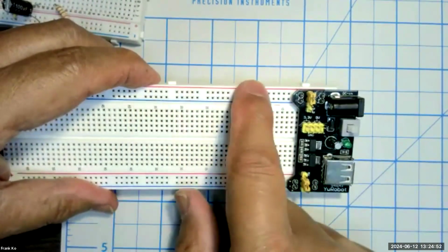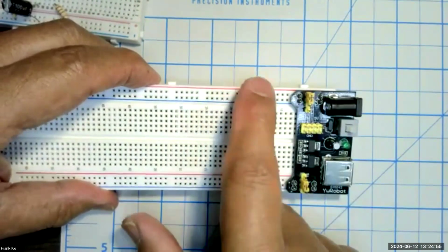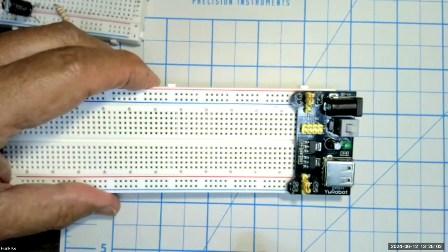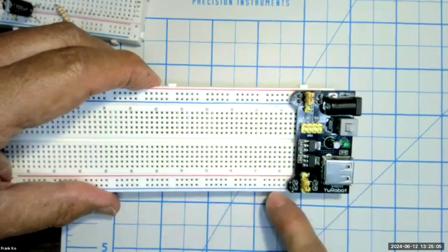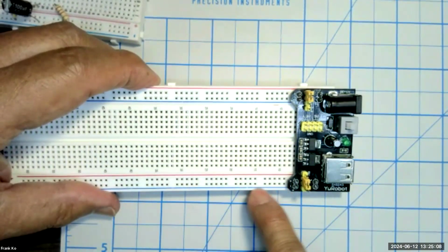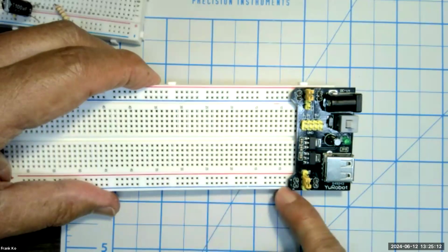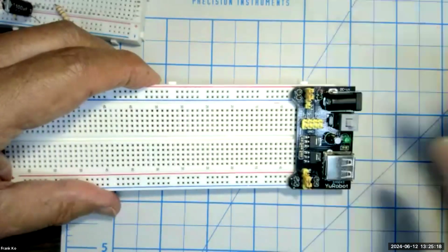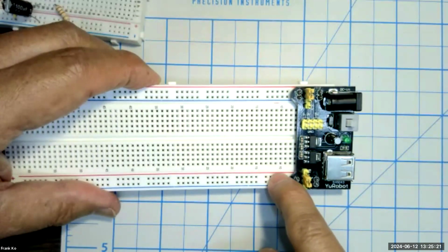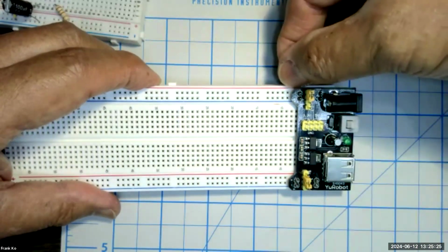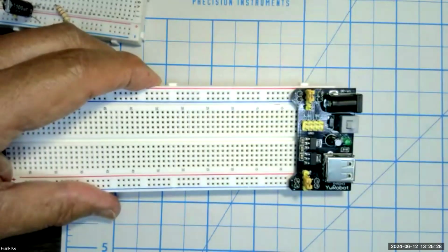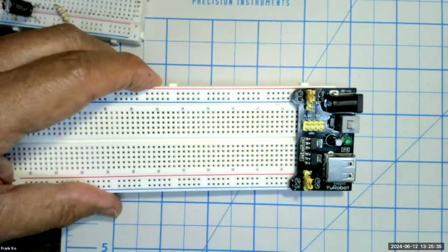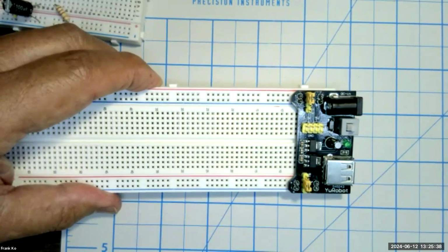This will be the power rail that will be supplied by the 5-volt source. And we will be connecting to these 2 rails. For convenience purposes, as the circuits continue to be more sophisticated, we can also use this blue rail here as a connection to completing our circuit. This blue rail and this blue rail are continuous with each other through the board, but there is no voltage that is supplied to this red rail. The voltage is only supplied through this upper red rail, but we can return our current through either this blue rail or this blue rail. More about that in a bit. So let's go ahead and pause for a moment.